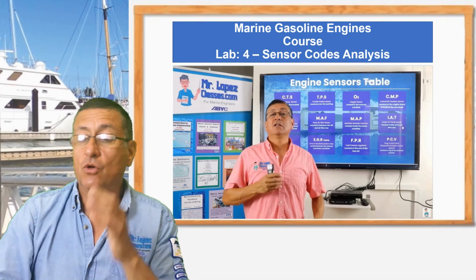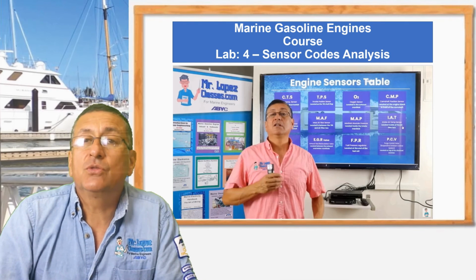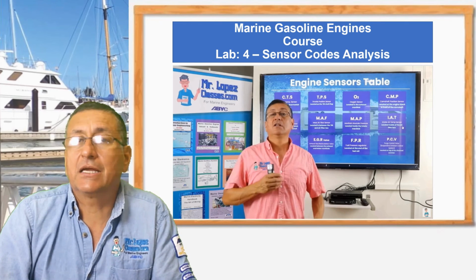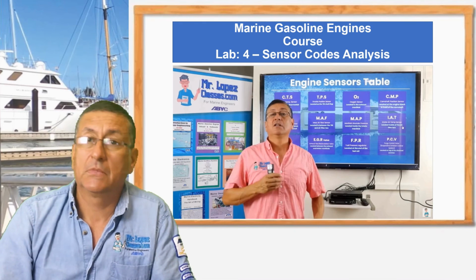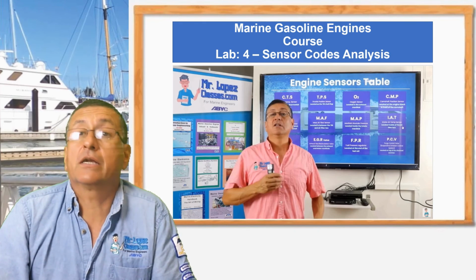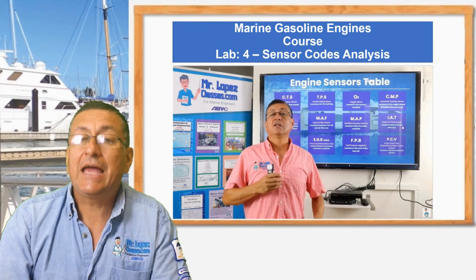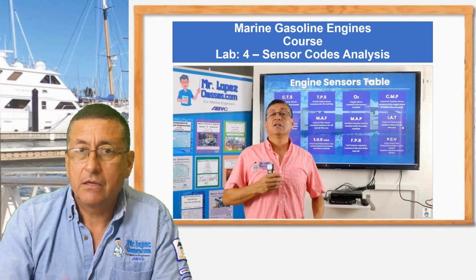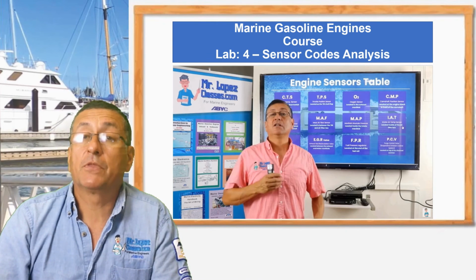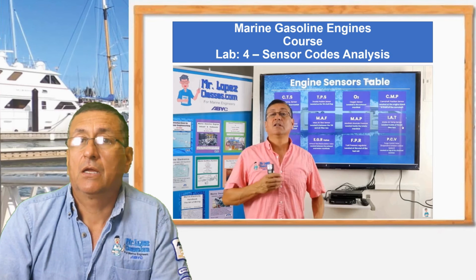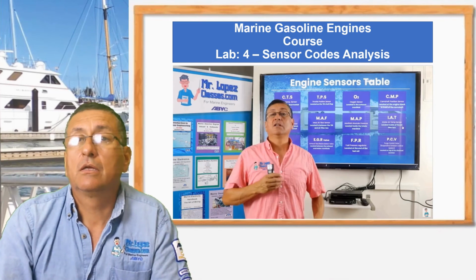to solve those problems. In other words, I want you to try to solve electrical, electronic, and mechanical problems without the scanner. Yes, in some cases the scanner is necessary because you need to clear the codes. But I need you to identify, with your knowledge, where is the problem. For what reason do I have the check engine light on?